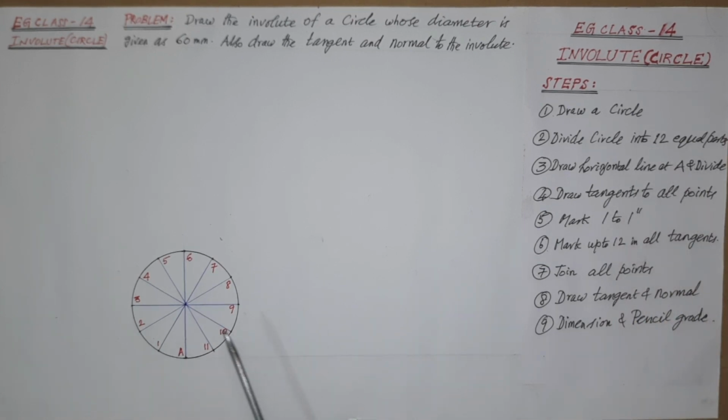That is, to draw the involute part, the circle is divided into 12 convenient number of equal parts based at the center point O. Now, draw all the lines at the circle center O using mini drafter with 30° each, and now give numbering in the clockwise direction at the circumference of the circle from 1 to 12, since the string end is released and lengthened to 12, the circular length of the circle for 12 parts.